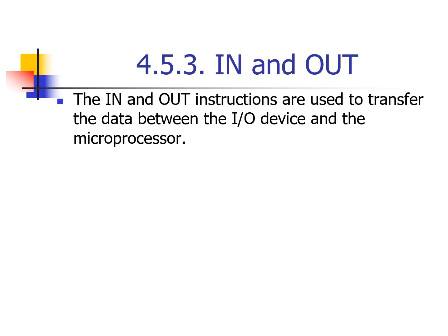IN and OUT. These are used with output devices, I/O devices. In, you're bringing in data from outside to your processor using an input port. Out, you're sending out data from your processor to the outside world through some devices, input device, output device.